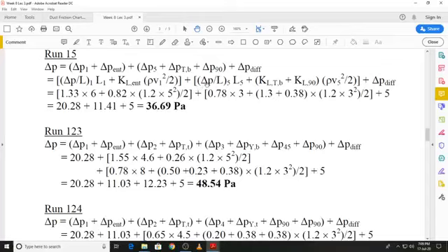And again we have the frictional pressure drop per unit length for segment 5, which was 1.55, multiplied by the length of segment 5, which was 3 meters, and then the dynamic loss can be calculated for both the fittings by adding up the loss coefficients of the fitting, because the half rho v square term is common to both.